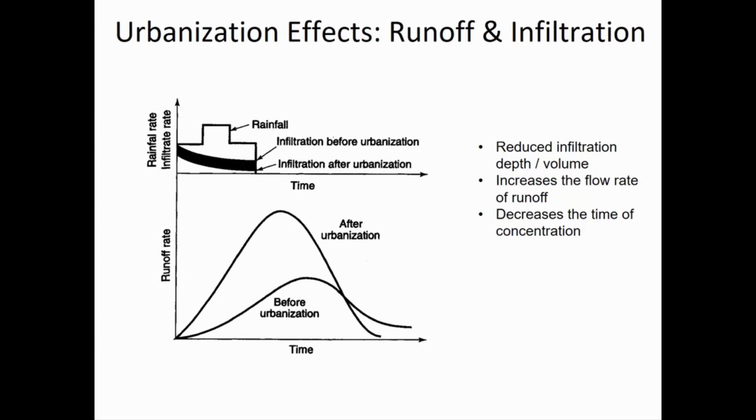This figure is showing two things. The hydrograph, which I've just shown you, and above that, what is called a rainfall hyetograph. The hyetograph is breaking the rainfall up into distinct periods. Rather than measuring it continuously, they're reporting an average during a certain period.